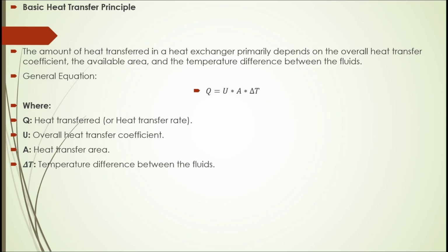Basic heat transfer principle. The basic equation is Q equals U times A times delta T. This means that heat transfer depends on the overall heat transfer coefficient, the heat transfer area, and the temperature difference between the fluids.